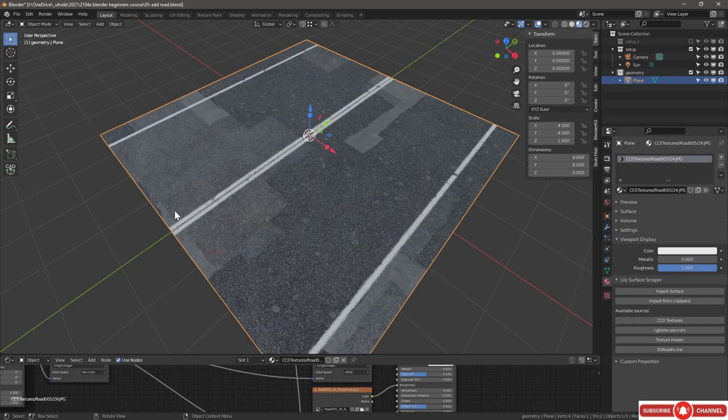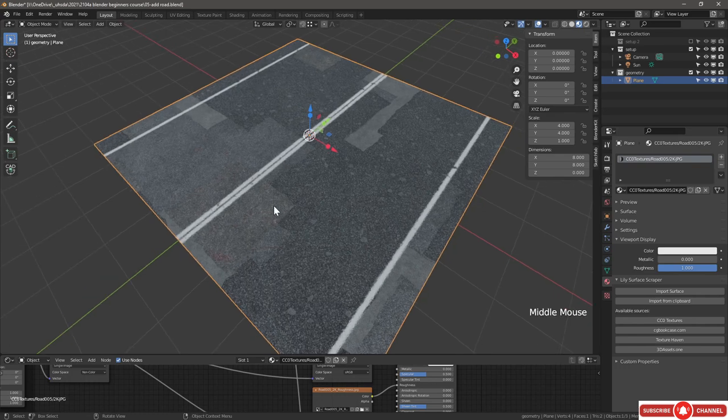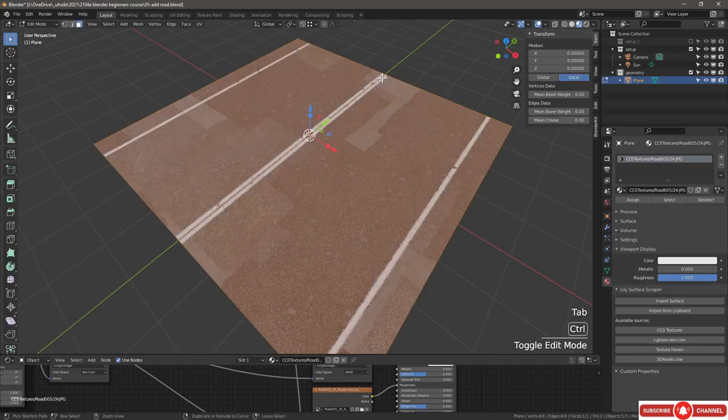We want to use only half of it so we can model our sidewalk and our curb and have that mirrored on the other side. So now if we go into edit mode, press Ctrl R, and Ctrl R creates loop cuts. Now Ctrl R only works with quad geometry. So quad geometry is any face that has 4 vertices. So that's sort of the basis of mesh modeling. We always need 4 vertices to work with, and then we can subdivide our mesh easily.